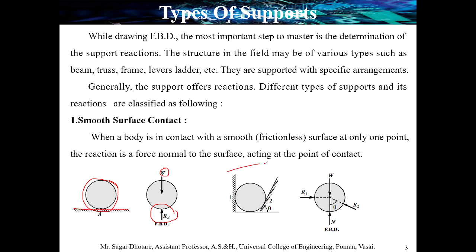In the second problem, or you can say second sample, a ball or a sphere is placed in between a particular stack. Okay, where there are three faces of contact. So first face of contact is over here. This is a bottom contact, and the third one is an angular contact. So there are three reactions which occur.